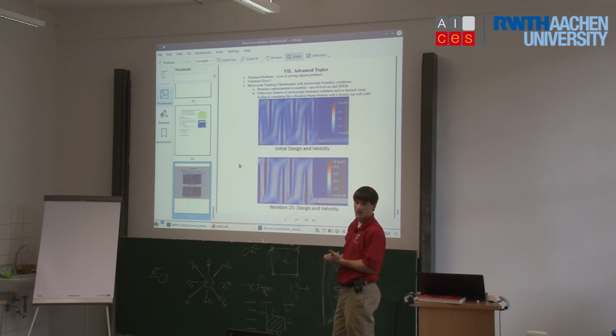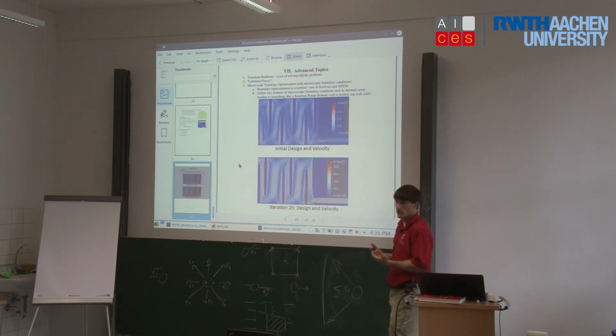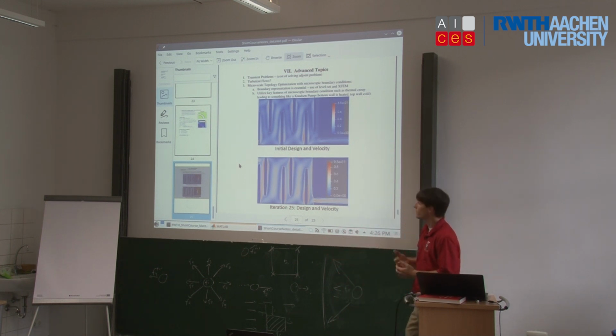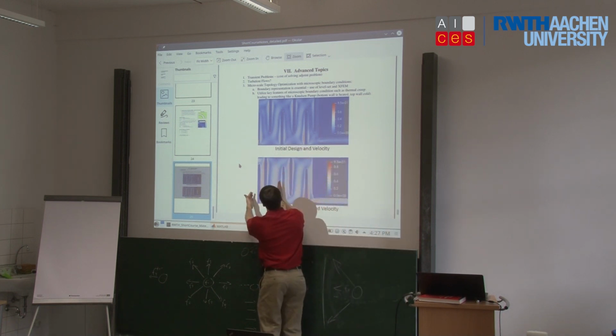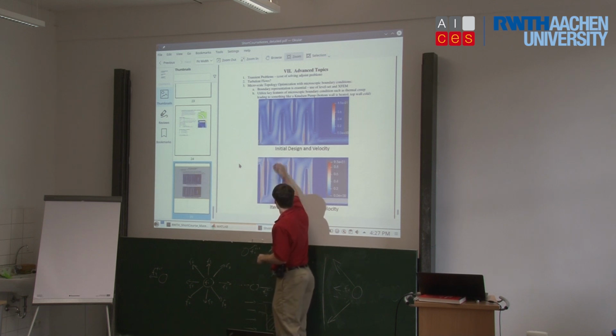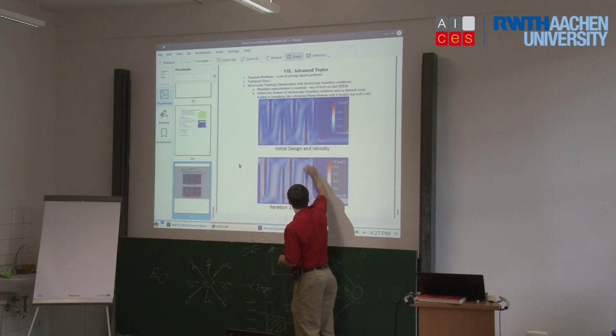And that temperature gradient is going to cause the fluid to flow down the side of these fins. But it's really a boundary phenomenon. It's something that you would not observe at a macroscopic scale. Okay? And so what you can actually do is by generating smaller and wider channels, you're generating a high pressure drop in this direction, a low pressure drop in that one, a high one here, a low one here, high one there.